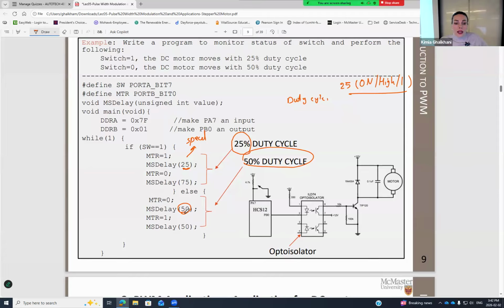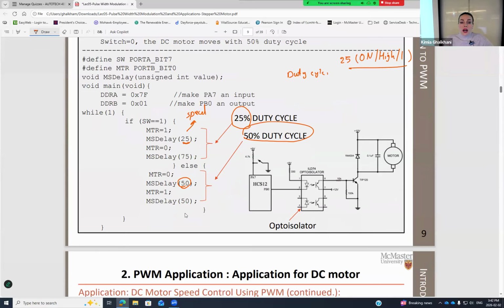And so on. Therefore, in this example, I'm using pin 7. You may want to use pin 4. Tomorrow I'll tell you. Give data direction to A. Suppose this is your port. We don't have port A on the actual microcontroller. This is an example. Suppose you are going to have port A, then give it data direction to become 7F. Your B is PB0, meaning port B bit 0 is going to be output. This is your output, this is your input.